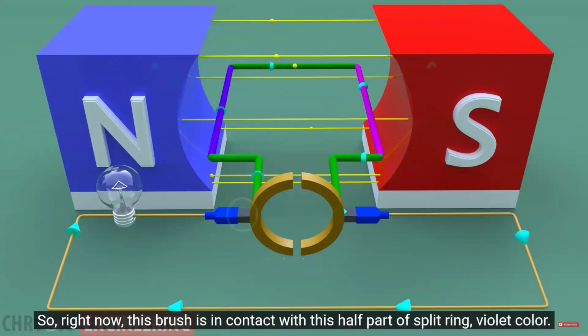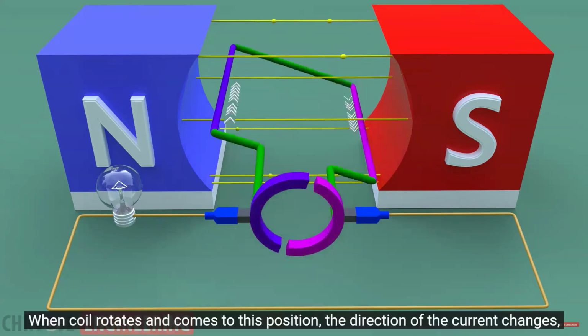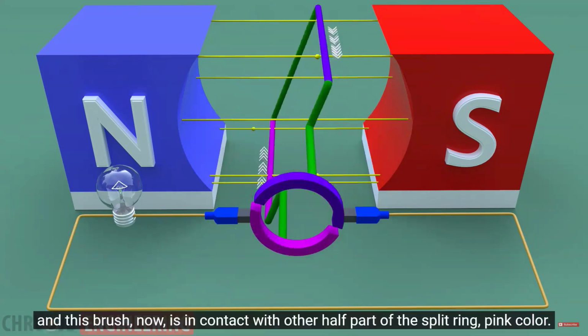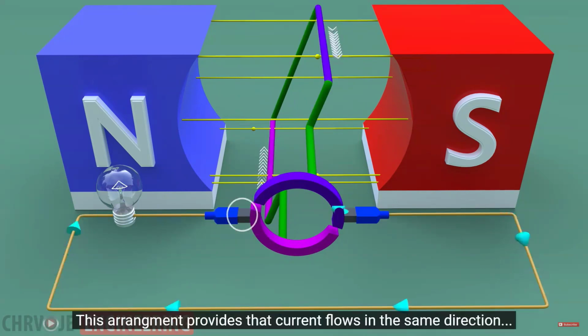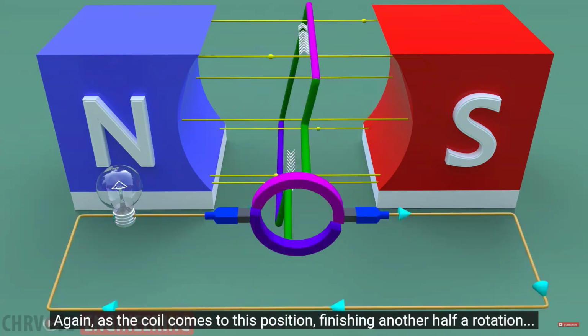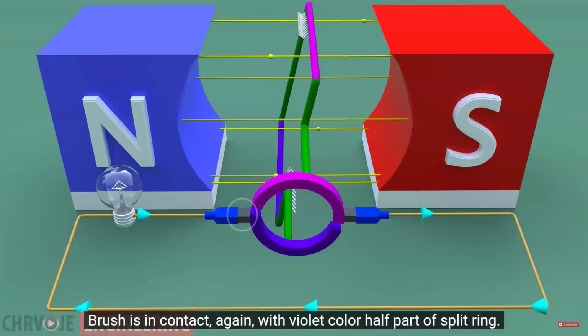So right now this brush is in contact with this half part of the split ring, violet color. When the coil rotates and comes to this position, the direction of the current changes, and this brush now is in contact with the other half part of the split ring, pink color. This arrangement provides that current flows in the same direction. Again, as the coil comes to this position, finishing another half a rotation, you can see that this has only changed contact. Brush is in contact again with the violet color half part of the split ring.